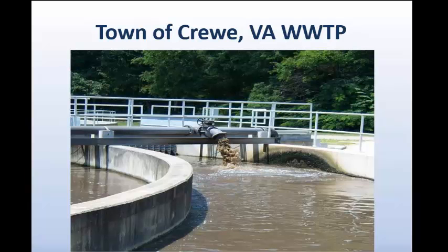And working on the exact same principle as those discs do, surface agitation imparts dissolved oxygen. So having these pipings discharging that high above the surface, as you can see in the picture, created a lot of surface agitation and as a result imparted a lot of dissolved oxygen.